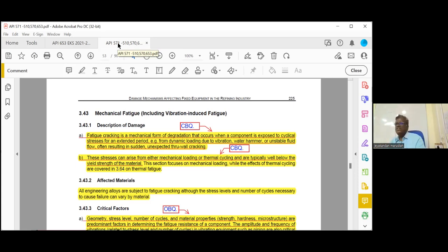What is meant by surface notch? A weld undercut, weld ripple, grinding mark, tool mark, arc strike, punch, hard stamping, drilled hole. These are considered surface notches. If there are weld ripples, that's why if any vessel or piping is in fatigue service, you have to flush grind everything. You have to make a smooth grind.